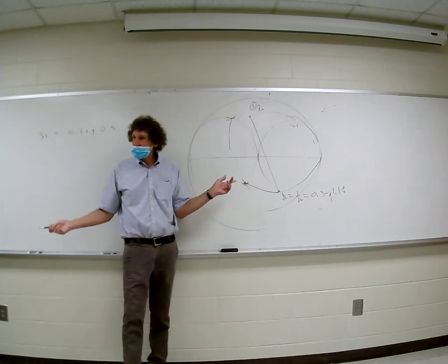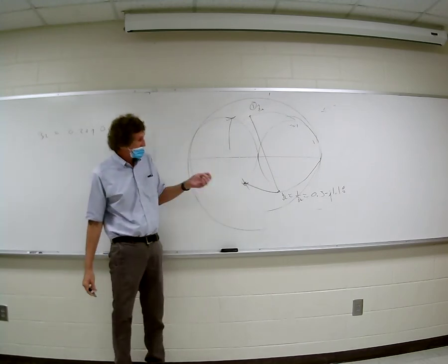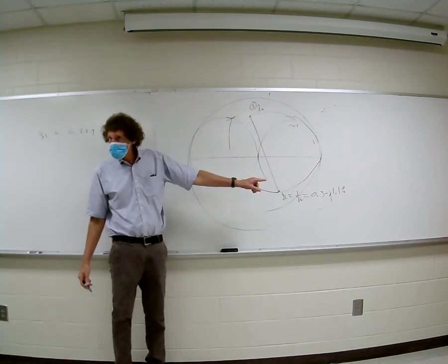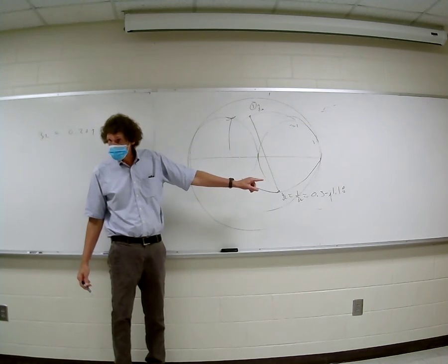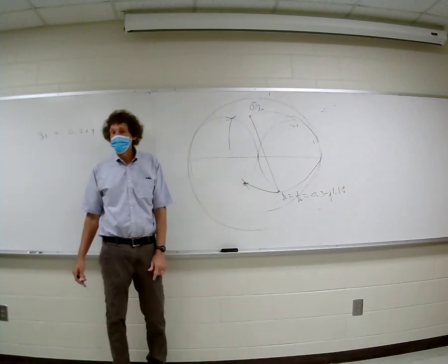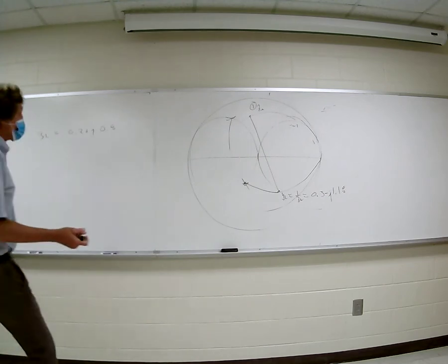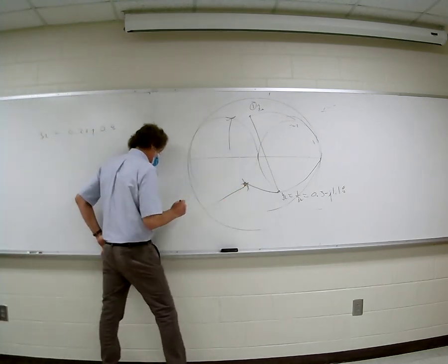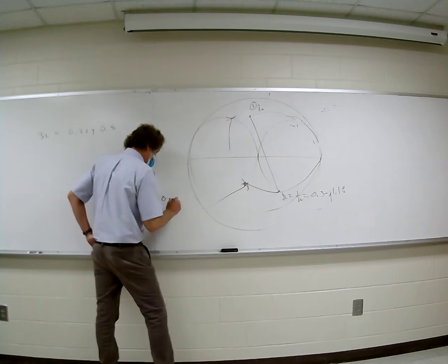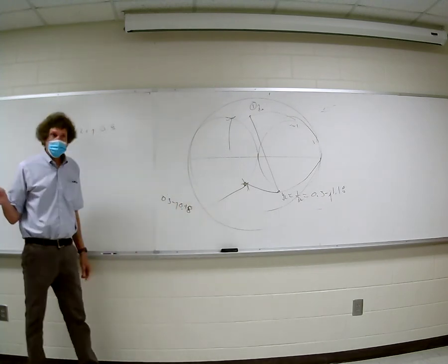You ask me about this, it's a good problem. Makes you think. So down here, what's the value? Now, in either case, what are we adding? We're adding a positive value, j, aren't we? Correct, class? So positive j to here and positive j to here. But what's the value to get to here? Remember, we're in the admittance, right? Well, what is the value of the point for starters? 0.3 minus j0.48. Do you all agree with that?